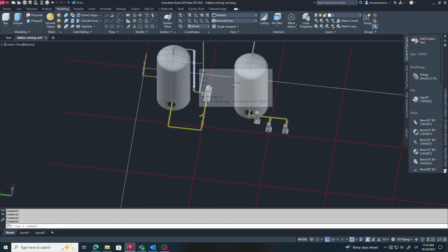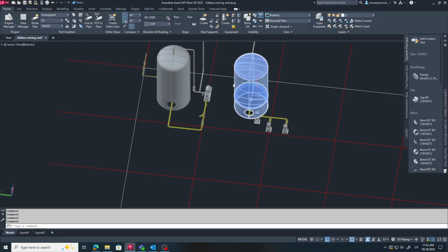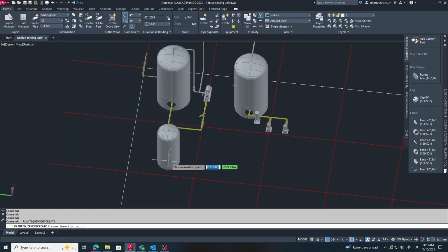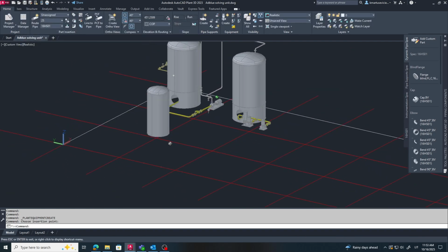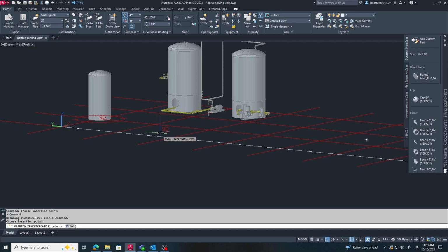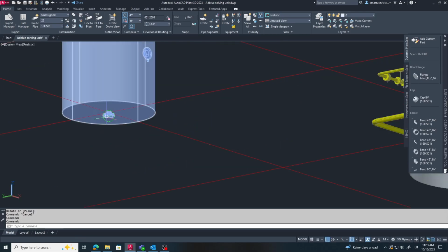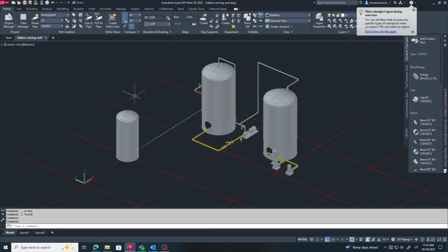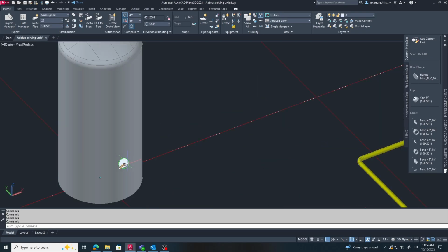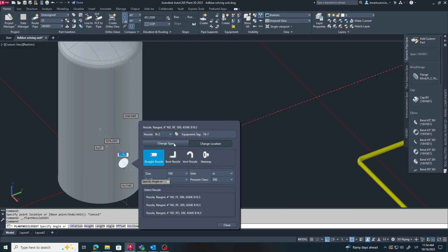The next step will be to place our storage vessels, where final AdBlue product will be stored. In this design, we will use 4 vessels. They will be slightly smaller in size, but using multiple units gives us flexibility, easier maintenance, and we can rotate vessels if needed. I will use vertical vessels because this type saves floor space and is widely used in real installations. Each vessel will have a simple discharge nozzle and a fill nozzle, so we can easily fill them from production and discharge product for loading or recirculation.